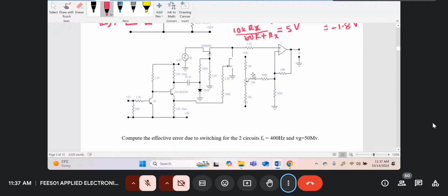And this is an offsetting circuit because all op-amps will have an output offset voltage, which should give rise to problems, like drift problems. So they use an offsetting circuit to ensure that when there's no signal, the output is zero.